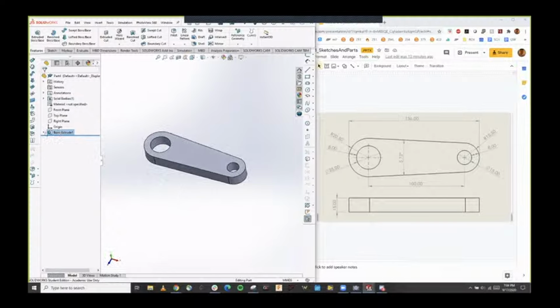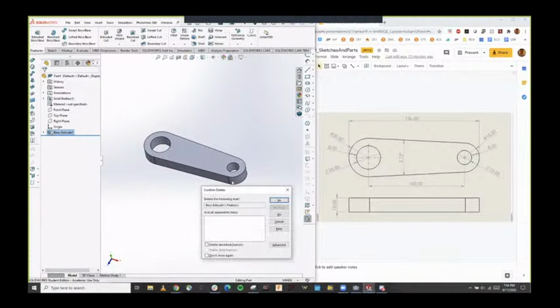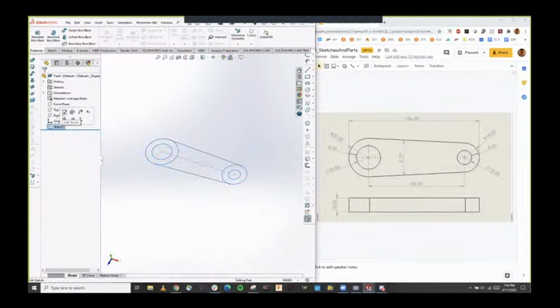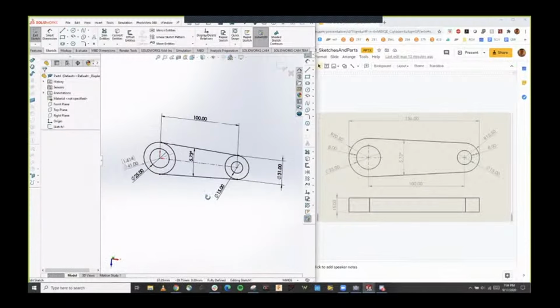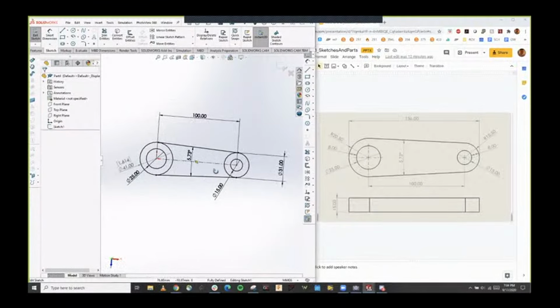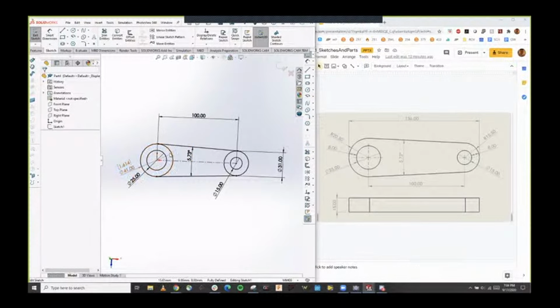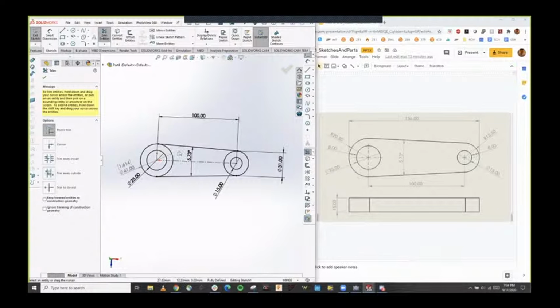Another way to do this, however, is if you actually go through and edit the sketch, there's something called Power Trim Tool. So this is a completely acceptable way to make your part. It's perfectly fine. But to be a little more accurate, you could also use the Trim Tool. So using the Power Trim Tool, you just hold down on one side of a line, drag it through an object, and as you see, it deleted the line segment between the intersection of this and the intersection of that. That's what the Power Trim does. It deletes everything between wherever the next two vertices are.